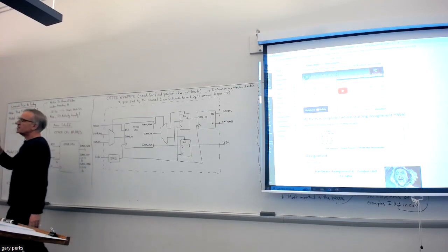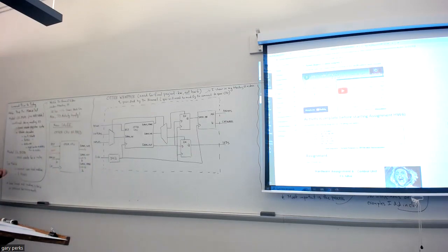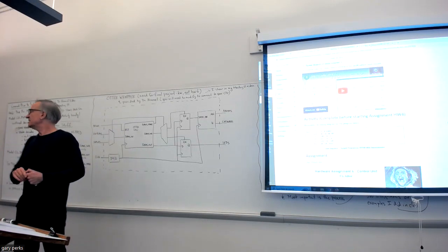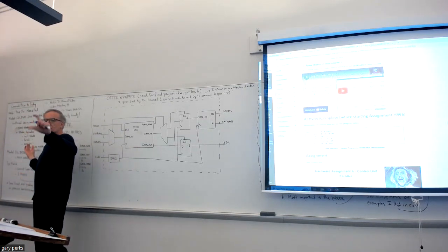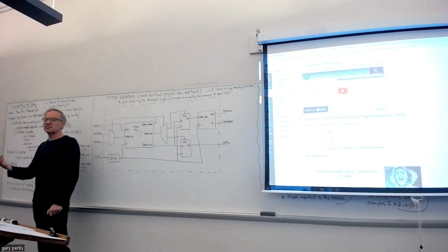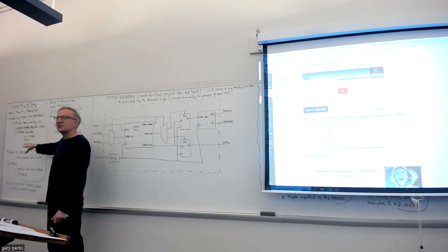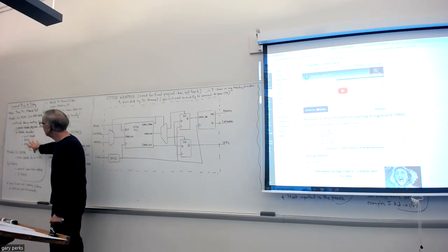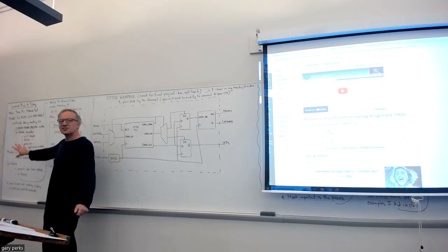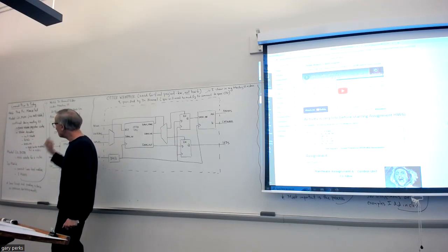So really, where the work lies is in the execute state, because that's when you have to look at the instruction and see what read enables and write enables have to be activated for that particular instruction. That's where your case statement is going to be, based on opcode. Again, I outlined it, so we're just going over things we already talked about, but I'm reminding you before we go on.